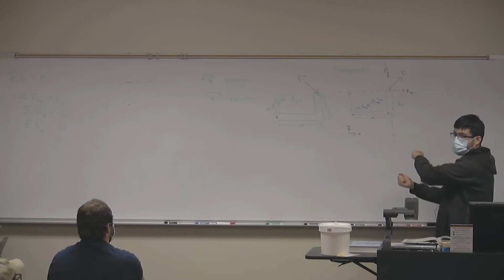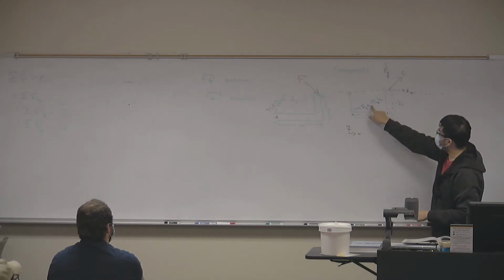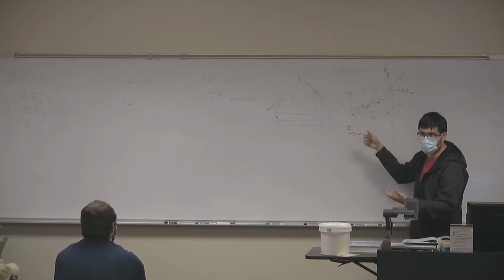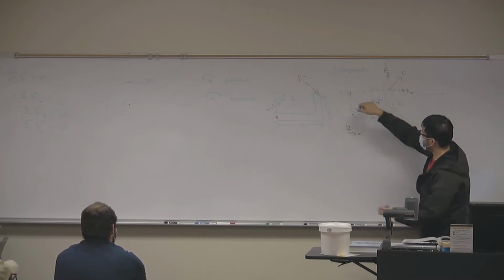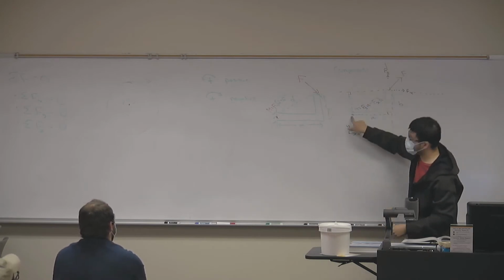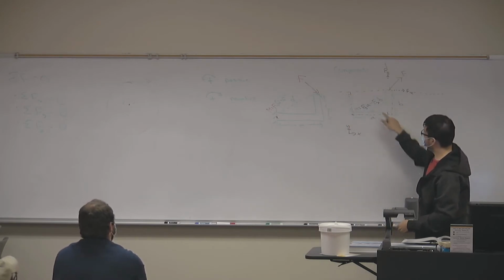Yep. Or the clockwise? Yeah. So my Fy is my force that causes a counterclockwise rotation, so that's positive, right? Okay. But then my Fx causes a clockwise rotation. Again, steering wheel, center of the steering wheel. So clockwise, so I add a negative sign.